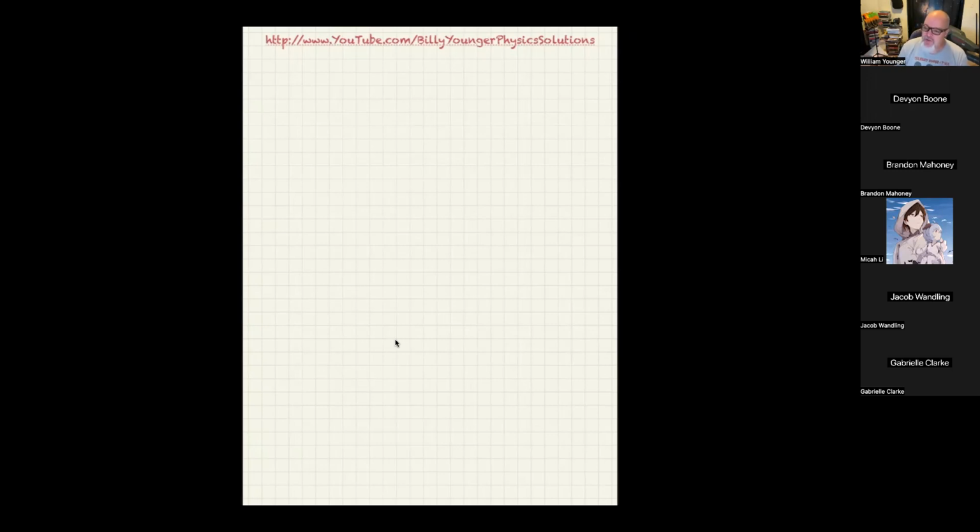And what you could do is treat the center of mass as if it's roughly some spot that you guess it is, and you call that the origin of the coordinate system that you're going to make. And then you just write out the X, Y, and Z components for each of the 3 particles or 4 particles or 20 particles there are. And what you'd see is, the bigger a mass is and the farther away that mass is from what you think is the center of mass, the bigger effect it has in causing it to tilt. So that might tell you, okay, I want to balance out the product of mass and distance. And that's about all the motivation I think is reasonable to give you.